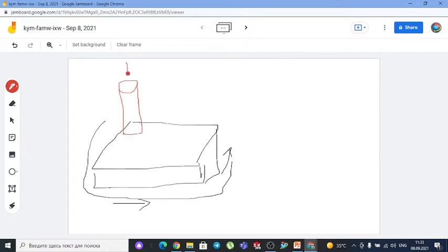The axis of the tool is perpendicular to the surface being machined. So we have seen this kind of milling operation. It rotates and removes material from the surface. In this case, the tool rotates and the table moves in the longitudinal and transverse directions. And the important thing was that the workpiece is fixed on the table. So this is what we saw yesterday for the milling operation.